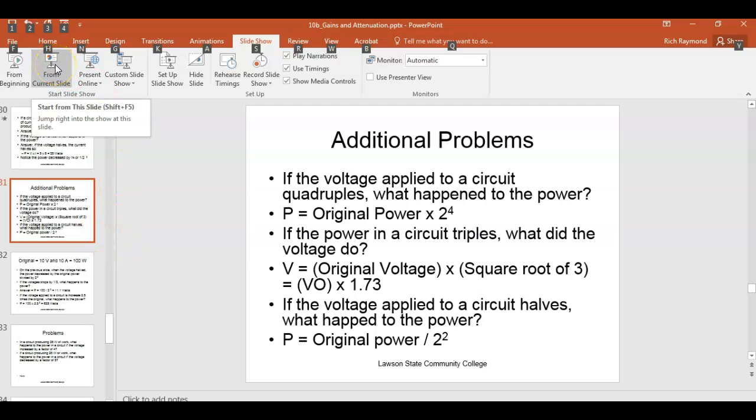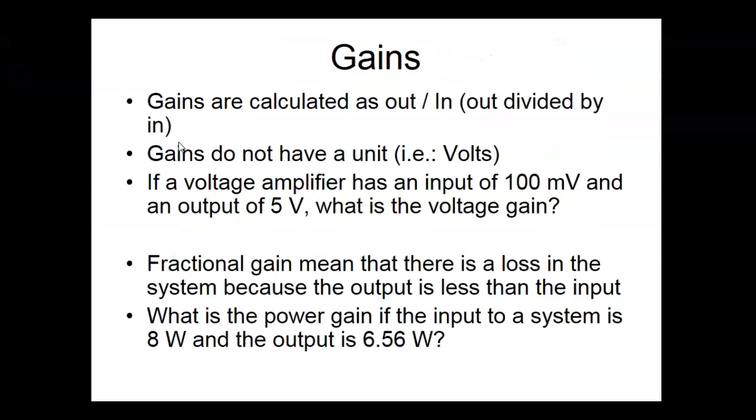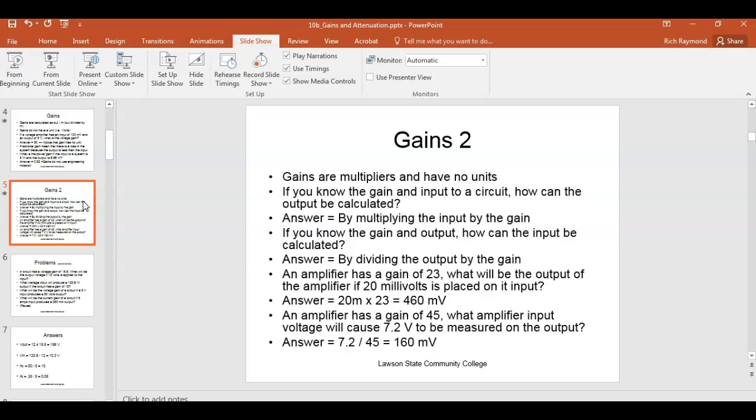So power varies with the square of the voltage, right? To a circuit, if the circuit does not change. So it means if I double the voltage to a circuit, power delivered to the circuit will quadruple. Y'all understand why? So power is equal to V times I. I is equal to V over R. You understand that? If R is the same, if you double the voltage, your current doubles. If you go down, it varies as 1 over. So if my voltage drops by 1/2, then my power is going to drop by 1/4. Y'all understand?